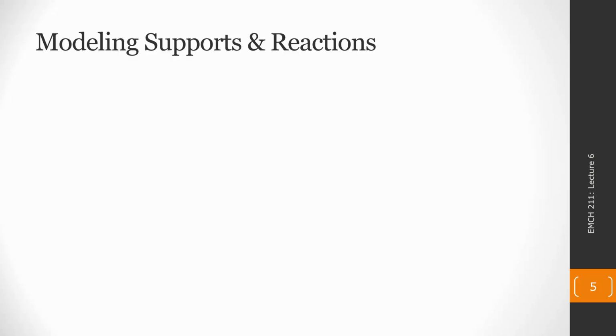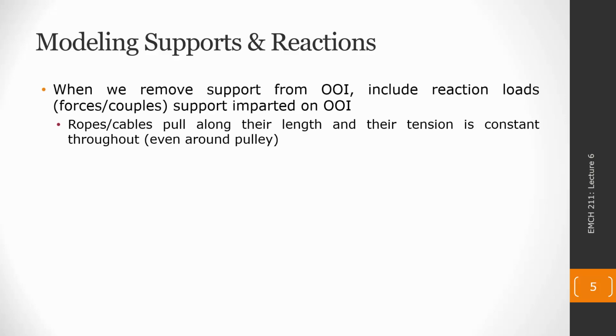Modeling support reactions in 3 dimensions is certainly harder than doing it in 2 dimensions, as there's twice as many potential motions that we have to consider, either the forces or the moments that that support is going to provide. However, the general rules for modeling are going to be the same in 3D as 2D. So still, we have to consider, when we remove the support from our object of interest that we are modeling, what that support does to the object that we kept.